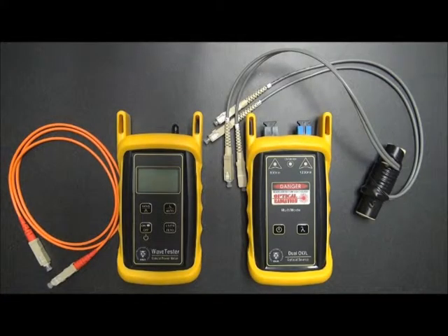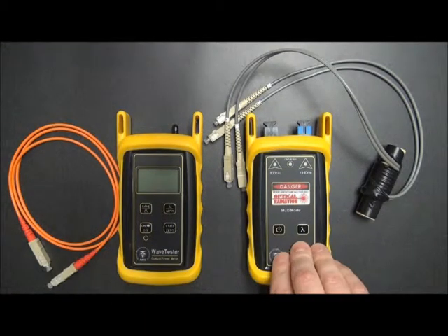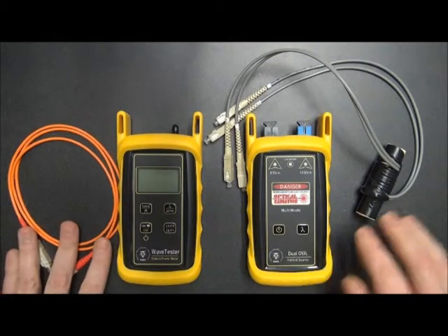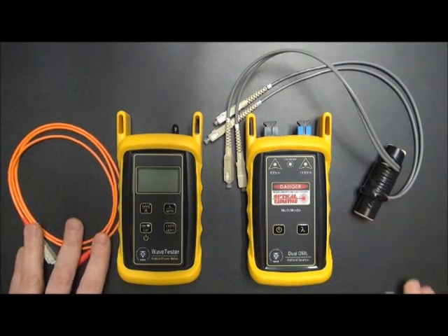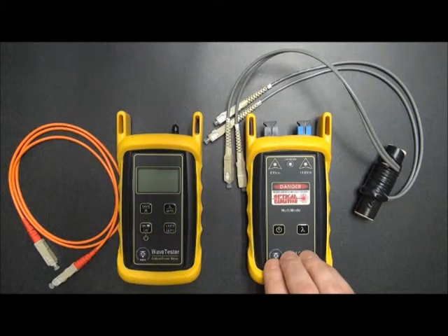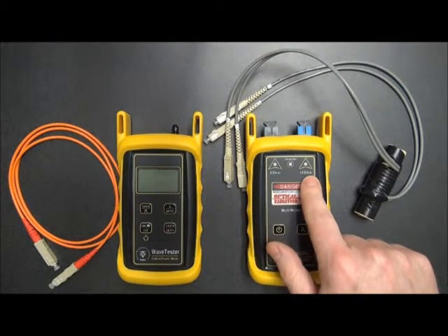As you can see here, we've gathered all the accessories and test equipment that we'll need for this test. In this case, we're using the WaveTester optical power meter and a dual OWL series multimode light source. Now, we also have 3 patch cables here. The reason we have 3 is because 1 cable will stay with the WaveTester when we do our measurements, but we also need a reference cable for both of the wavelengths,